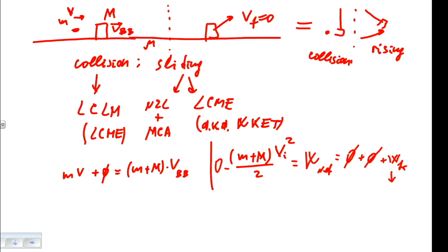For the work done by friction, we have an equation written just 5 minutes ago. -1 because of cosine, coefficient, normal force, distance traveled. Normal force in this situation is just mg. Everything is horizontal. And, sorry. When I said m, I meant total mass. So in this situation, that is total mass.